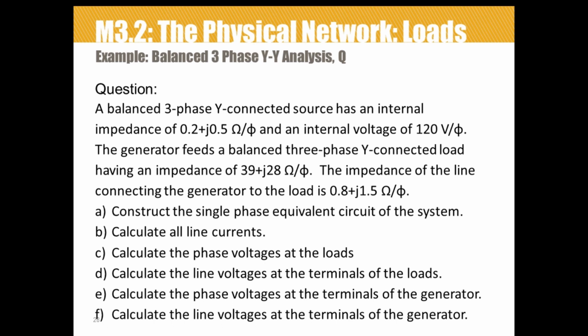Okay, so let's do an example of using the single-phase equivalency diagram to do a balanced 3-phase YY analysis. We don't actually have to analyze that whole circuit. We can just use a single-phase equivalent circuit to come up with a solution for one phase, and then we can apply the known relationships between the three phases of the circuit to determine the B and the C phase calculations. So the question is that we have a balanced 3-phase Y-connected source.